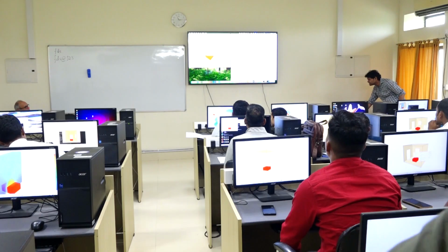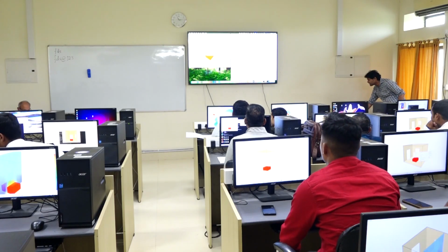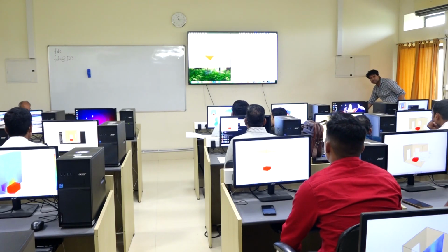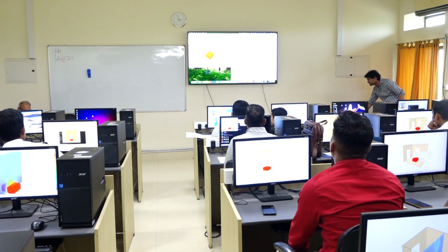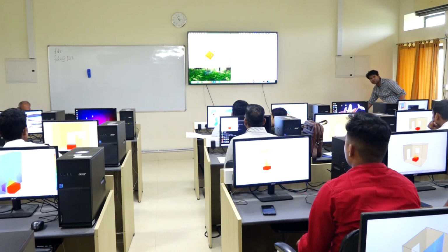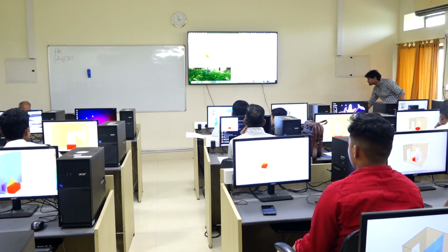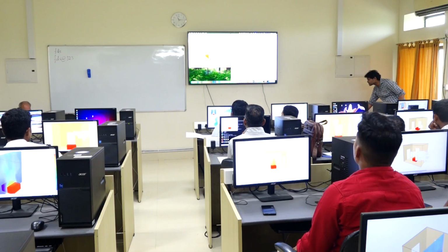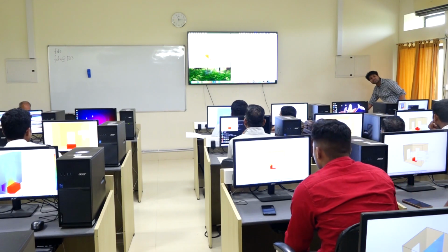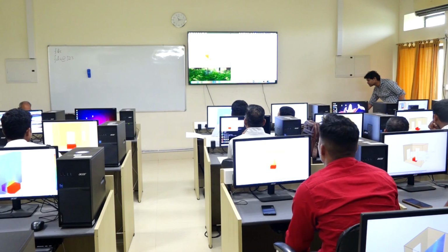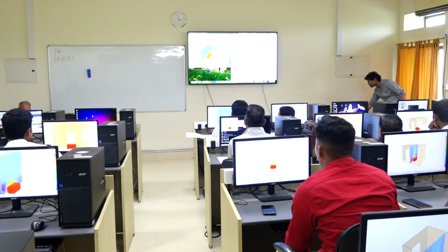If you want to see 3D smoke and just the temperature, let's say if you want to see the fire, you select the temperature. Okay? If you want to see the temperature distribution on the slice, then you go to slice, select the temperature, and then you select that slice, Y is equal to 2.0. Okay?